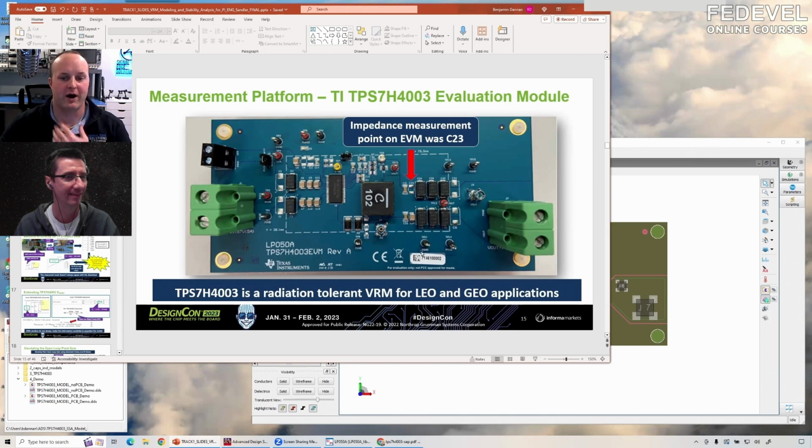Sure. To build one of these state space average models, we call this the Sandler state space average model, since Steve Sandler created this for ADS. This is what Steve Sandler teaches. He calls it the unified state space average model. It does DCM, it does CCM, voltage mode and current mode, all unified in one model. Show the model, I'm curious.